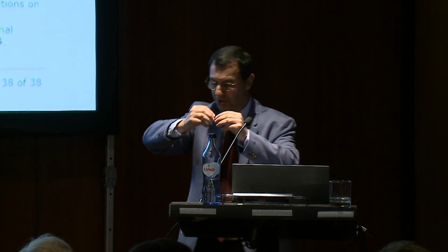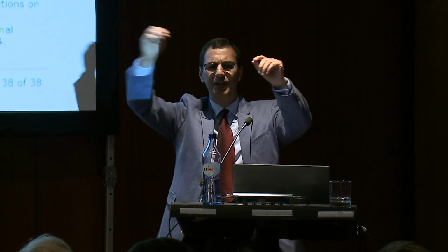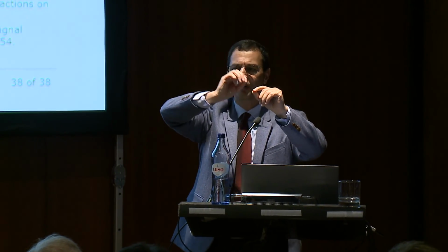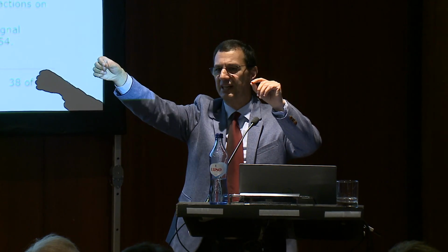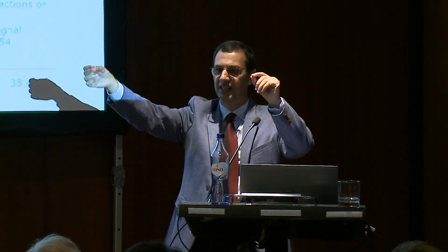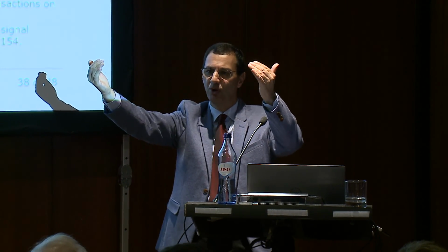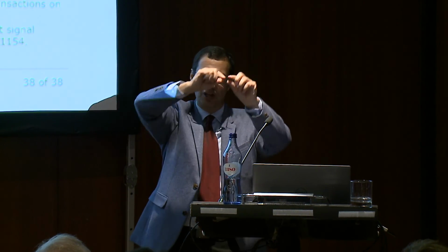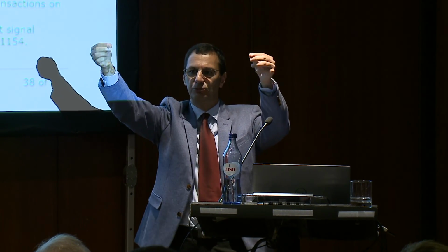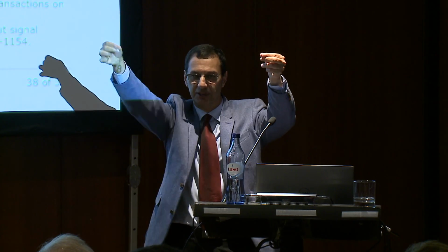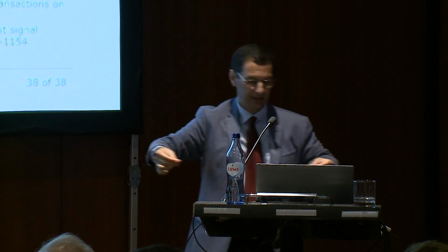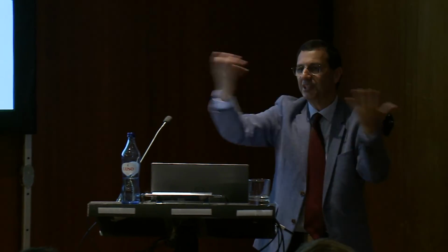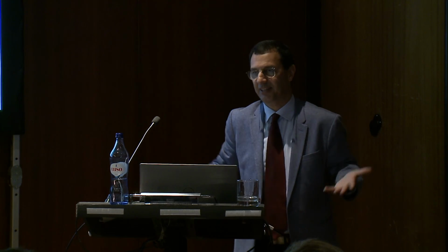So when I was talking about Miller's theorem, you know Miller's theorem is that you have a resistor that is connected between a node with a voltage V and another node that has minus A times V, let's say minus 10V. And that resistor could be made equivalent to 2 resistors that go from those nodes to ground. So instead of going from input to output, you become 2 resistors that go from the respective input and output to ground.